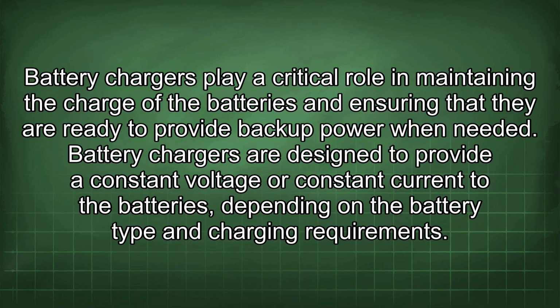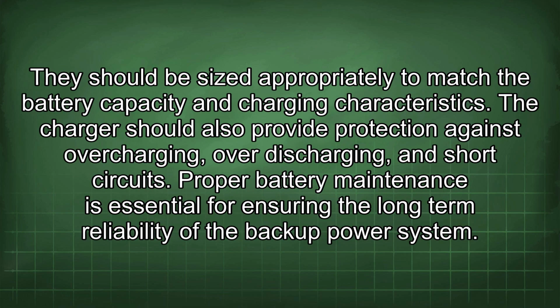Battery chargers are designed to provide a constant voltage or constant current to the batteries, depending on the battery type and charging requirements. They should be sized appropriately to match the battery capacity and charging characteristics. The charger should also provide protection against overcharging, overdischarging, and short circuits.